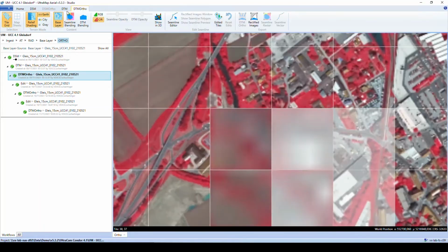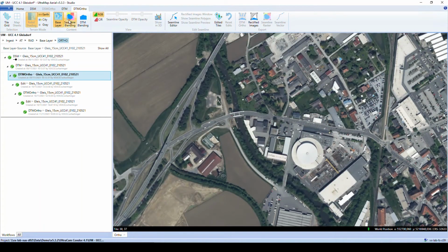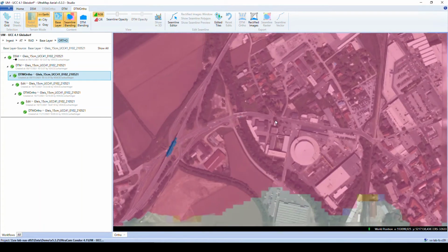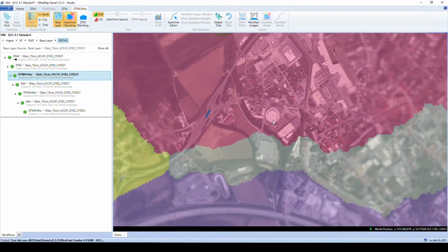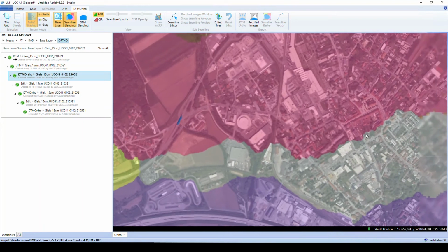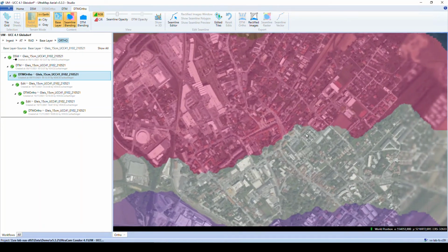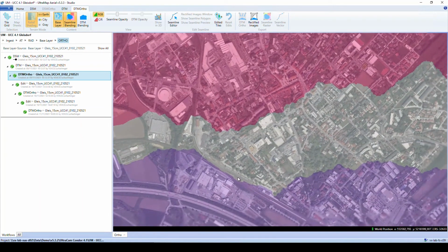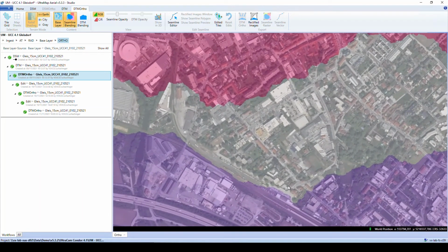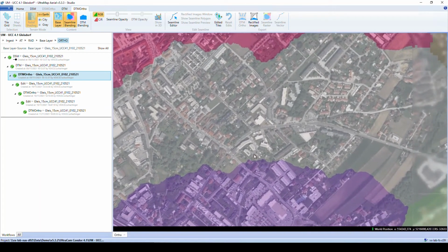The orthophoto is created by automatically placing seam lines. The seam line algorithm is using all kinds of input data which is available, so that's the DSM, the DTM, RGB and near infrared information. With that information it tries to find a path through the AOI which avoids cutting through any objects and tries to follow roads, buildings, and vegetation as well as possible.